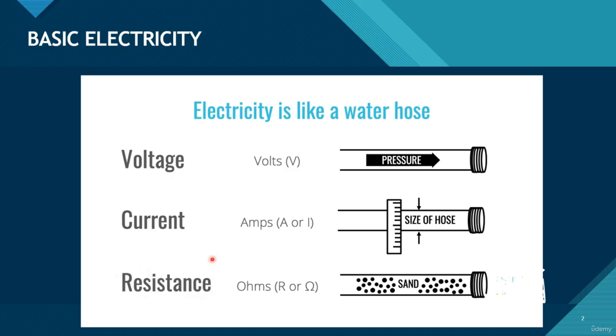And we'll need to take resistance readings to determine whether a compressor's windings are okay, whether they're open. We'll take resistance readings on the compressors to see if it's grounded to the casing, and resistance readings of contactor coils. So we're going to need to take a lot of these readings. Current, for example, if a compressor runs at 8 amps, and we're drawing more than 8 amps, then something is seizing that compressor. It's having a hard time turning. So we can tell whether that's happening by taking current readings.